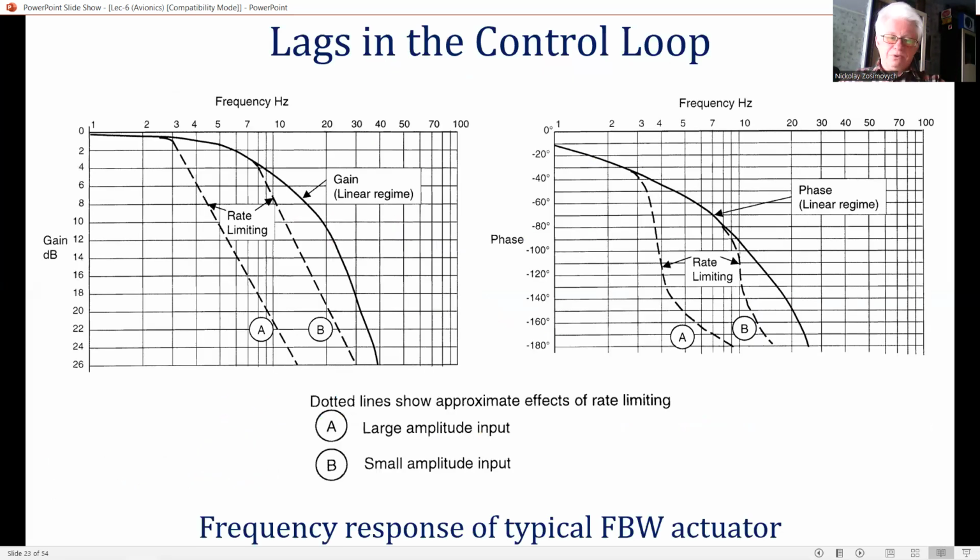The worked example has been very much simplified by ignoring the lags which are present in a real system, and by assuming a rigid aircraft. The object is to illustrate basic principles, and in particular the use of a proportional plus integral of pitch rate error control law to stabilize an aerodynamically unstable aircraft.